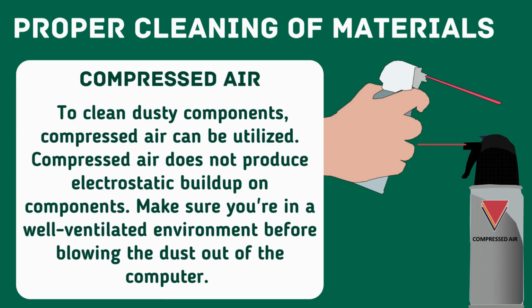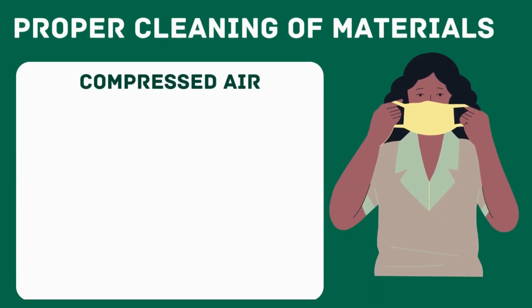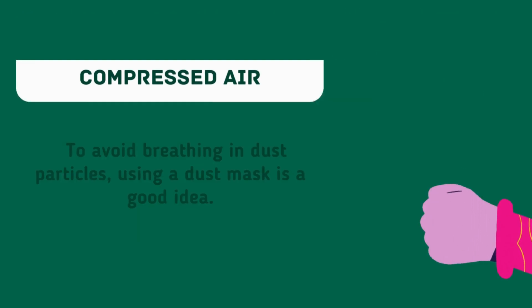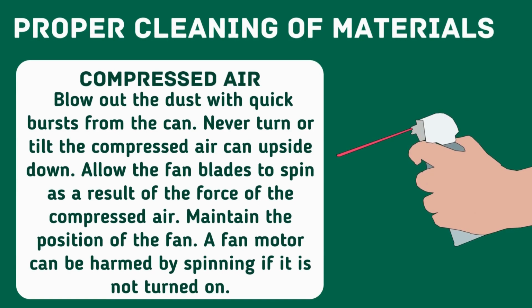Compressed air does not produce electrostatic buildup on components. Make sure you're in a well-ventilated environment before blowing the dust out of the computer. To avoid breathing in dust particles, using a dust mask is a good idea. Blow out the dust with quick bursts from the can.